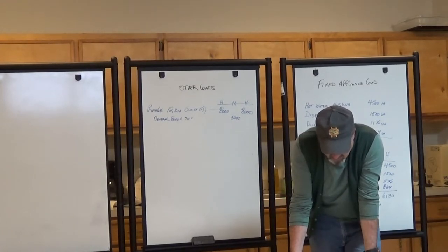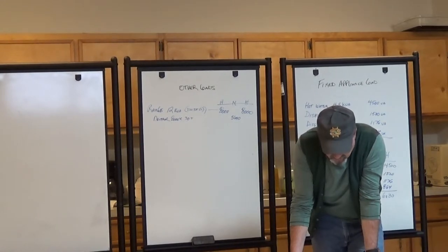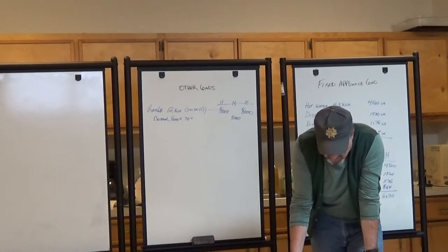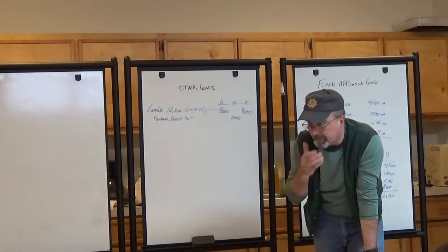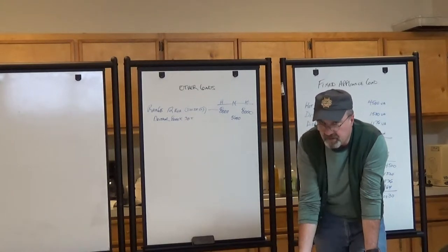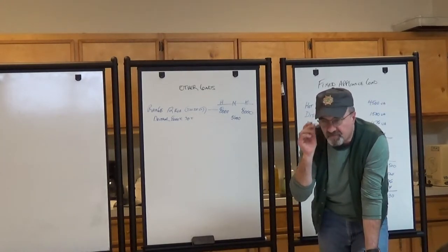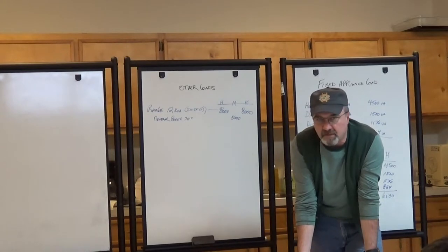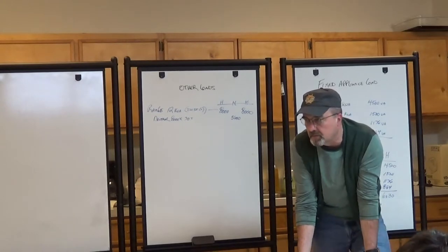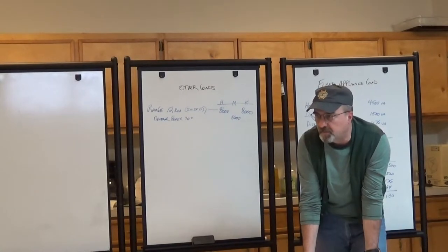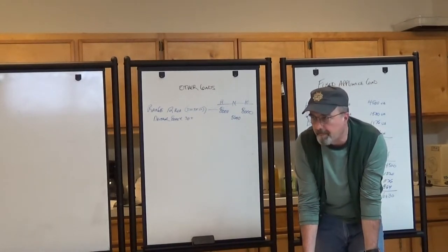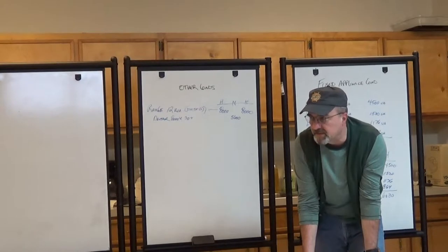So it says the load for the household electric clothes dryer in a dwelling unit shall be either 5,000 watts VA or nameplate rating, whichever is higher. Okay. So if the dryer was 4.5 kVA, what would be the demand that we would give to the dryer, based on what it says there?